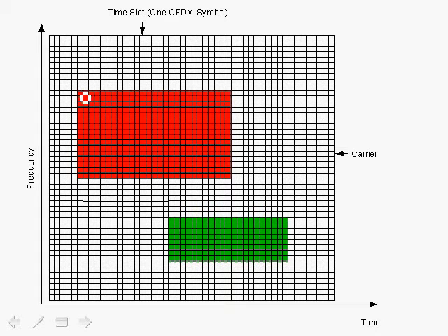So when it performs the forward FFT, it can actually extract the carriers associated with its data region and then decode the data up to the number of time slots allocated for its region. So it knows how many carriers and how many time slots are allocated, and as it performs a forward FFT and obtains the carriers, it then decodes them and it obtains its own data, which was sent to it by the base station. Of course, we're simplifying here tremendously, just ignoring forward error correction code and just assuming that each carrier contains data.